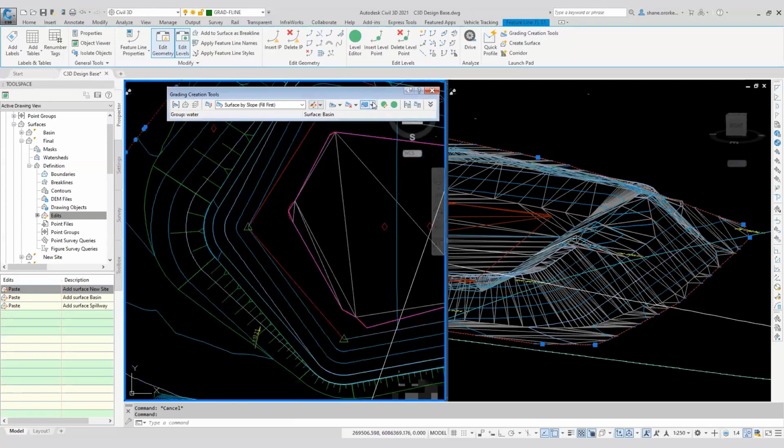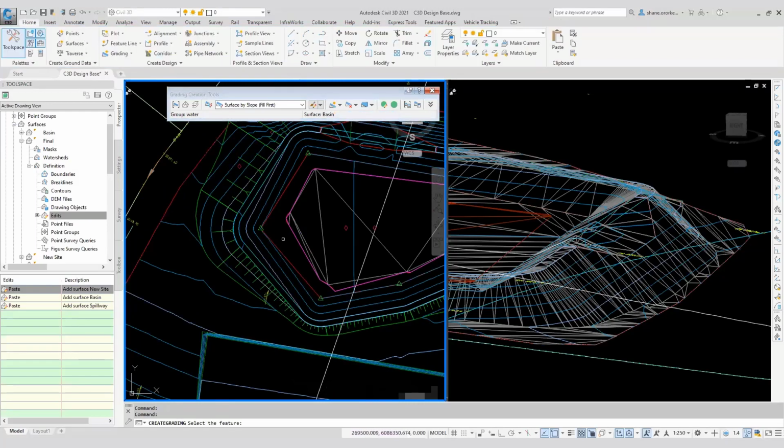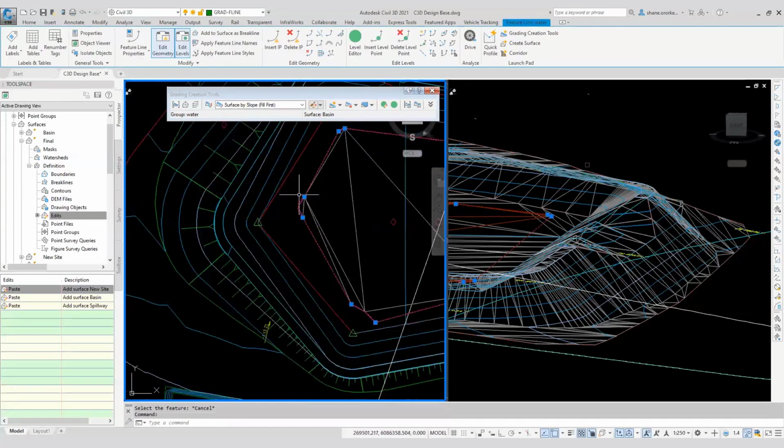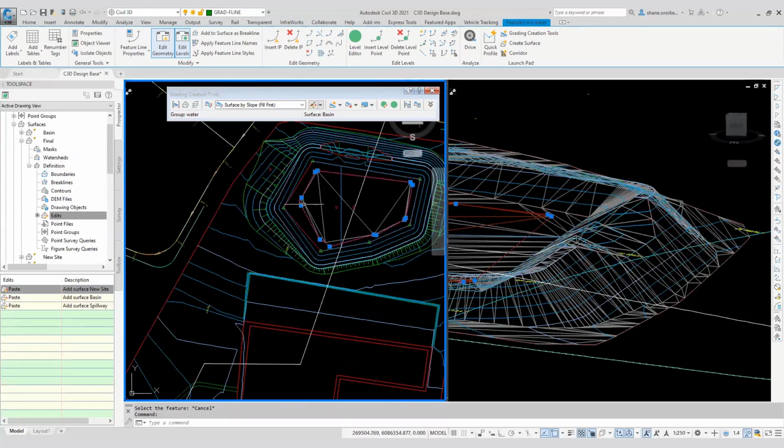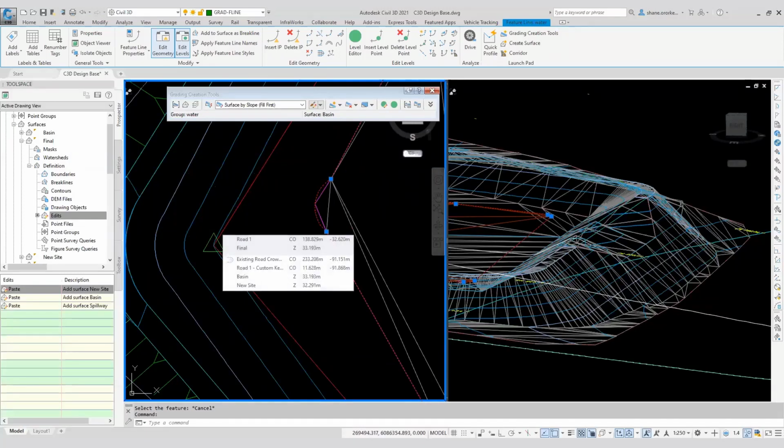In my case, I think the problem is I went too low. So I think I went underneath the water at this end, because this isn't a flat bottom. So I don't know if the grading was actually a problem so much as my elevation here. So I think what I need to do with this is actually raise it up. I'd say that that corner is lower than the bottom of the basin. Was it 32.4 versus 32.1? Yeah, should be right.